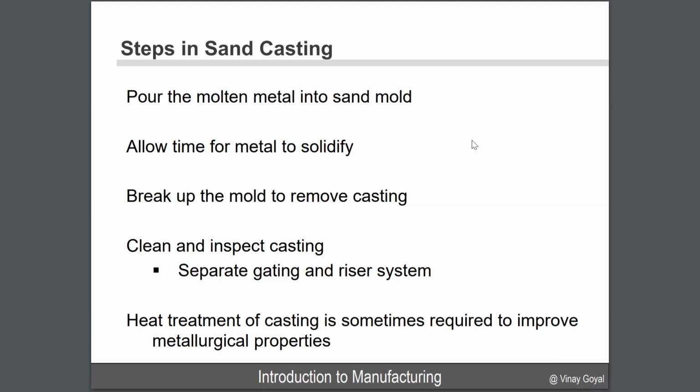Another approach people have used for inspection is X-ray, which can also find defects within the casting that cannot otherwise be found. So two very good approaches are used. And the last aspect is that heat treating cast parts can really improve the properties of the part by allowing better mechanical properties to be achieved.